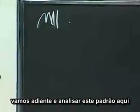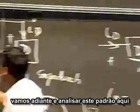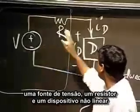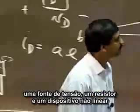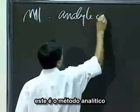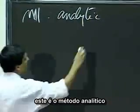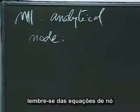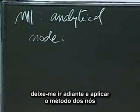Method 1 of analysis. So let's go ahead and analyze this pattern here. This template circuit, if you will, a voltage source, a resistor, and a nonlinear device. This is the analytical method. And remember, the node method applies. So let me go ahead and apply the node method.